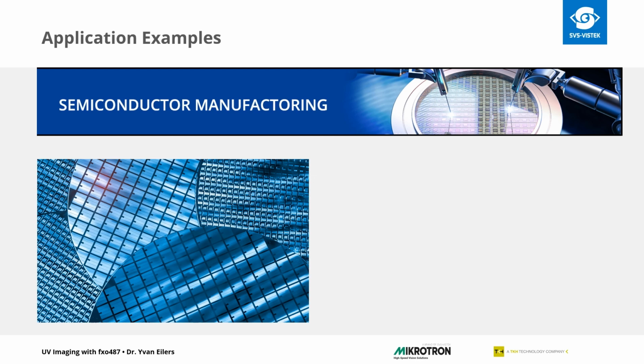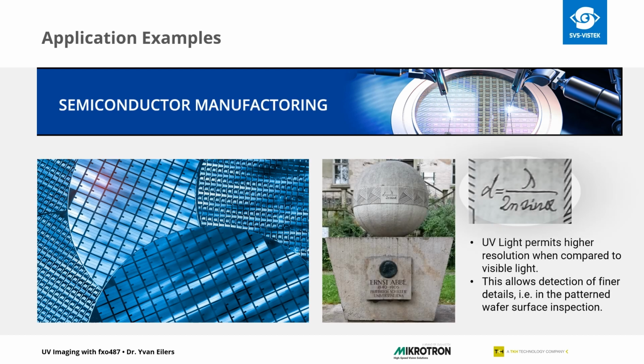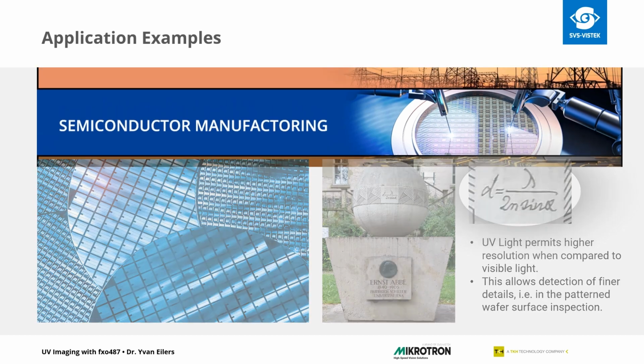Another big reason to use UV light is its resolving power as described by the diffraction limit of light. The diffraction limit d is the overall limit of the smallest details you can resolve with an optical system. As you can see from the formula, the diffraction limit has a linear dependence on the wavelength lambda. UV light, with its shorter wavelengths than visible light, allows us to resolve smaller structures than visible light.